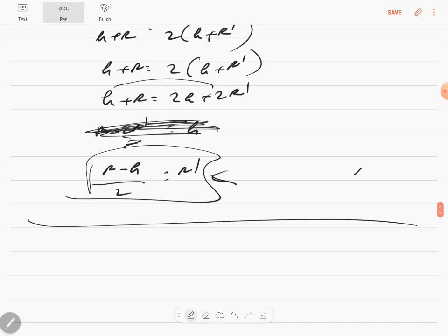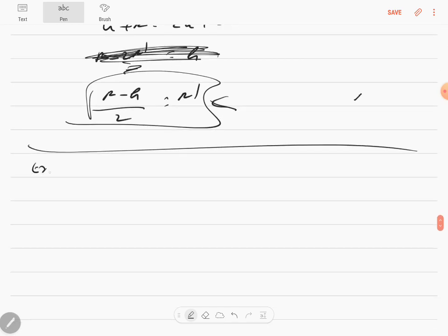Then as the next sum, which is example 98, I'm sorry. The voltmeter reads 5 volts at full scale deflection. For the full scale deflection, it reads 5 volts and is graded according to its resistance per volt at full scale deflection as 5000 ohm per volt. Okay, it's graded according to the resistance per volt. What is given is a resistance per volt. I don't know what is that. They've given resistance per volt.